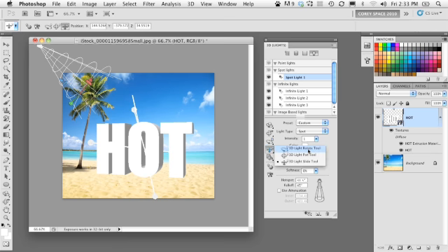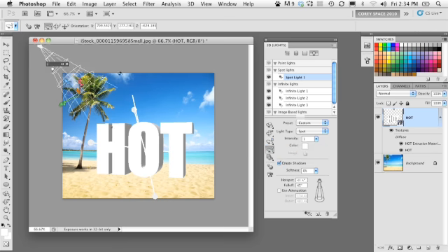And then we can use the 3D light rotate tool to move it around and illuminate the object based on its positioning. I'm also going to go ahead and widen the scope of the light. Notice how it's a narrow cone of light here? Well, if you go into the 3D panel with the light section activated, down here toward the bottom, you've got the fall off. I'm going to go in there and increase that to around 70, and you'll see the scope of the light just got a lot wider.